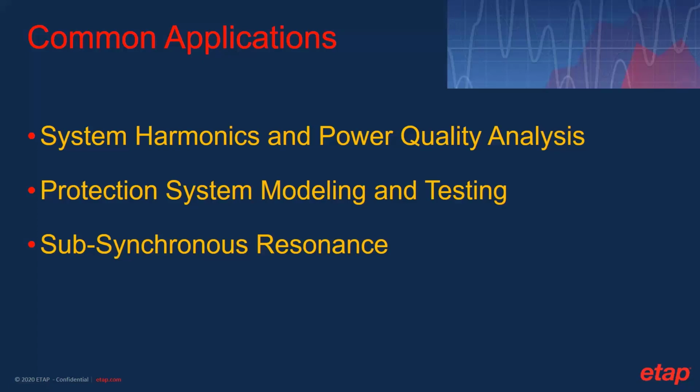Protection modeling, protection and relaying. Once again, you have dedicated RMS type protection and relaying study programs. You don't use EMT programs on a day-to-day basis for protection system studies, but if you want to analyze certain specific details such as issues with CT saturation, or designing of complex controls on a high voltage series compensated line, then it's again common for engineers to verify your design in an EMT type environment.